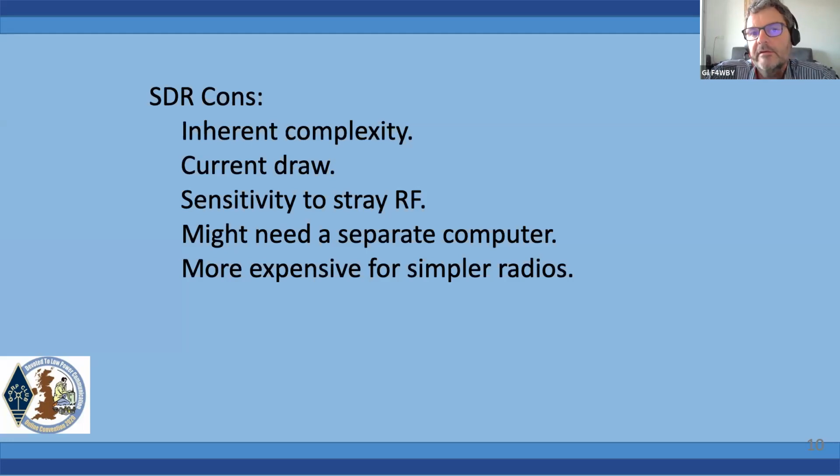There are radios on the market today that will draw 1 to even 2 amps on receive, and as soon as you key the mic, your wires melt, because it's drawing 30 amps all of a sudden. But my MTR3B for instance, for a 5-watt output, draws about 700-800 milliamps. So that's very efficient. Of course, the SDRs with all those circuits inside, and digital signal processing, and maybe a color screen and all that stuff.